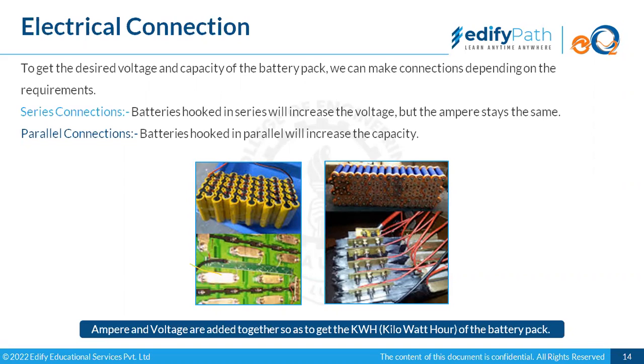When we assemble the battery, first of all we connect the cells in parallel to form separate modules. We know 2.6 Ah is the capacity of every cell, and say we want to achieve 500 Ah. Then we would connect around 20 cells in parallel to achieve that Ah.